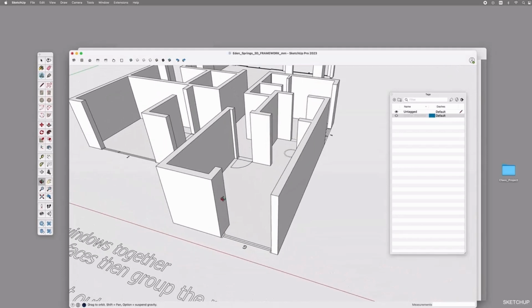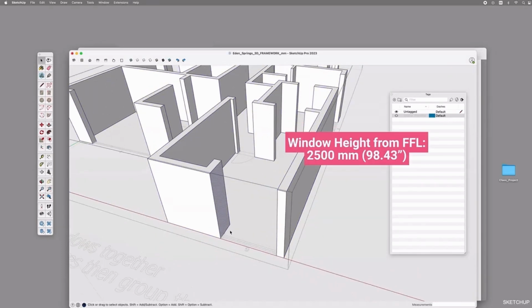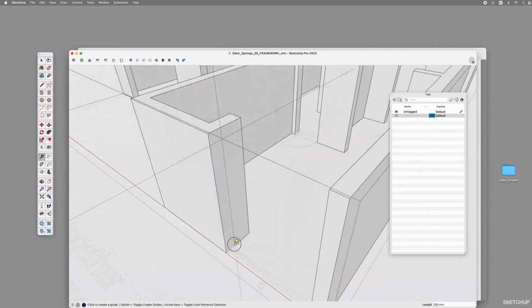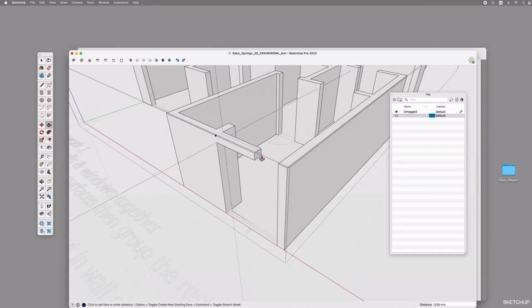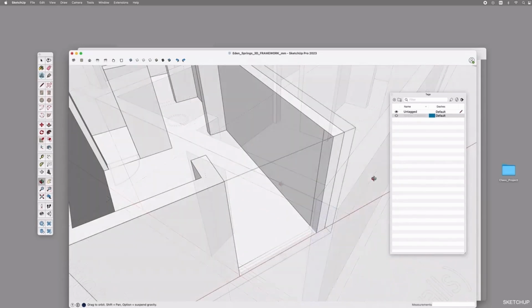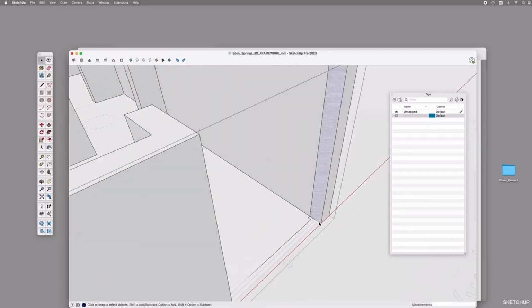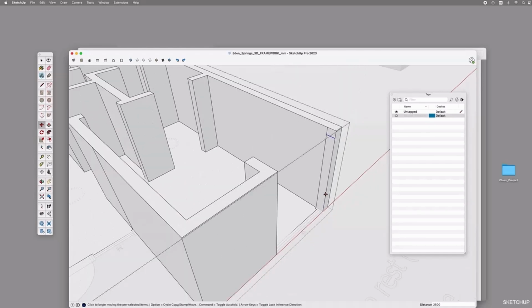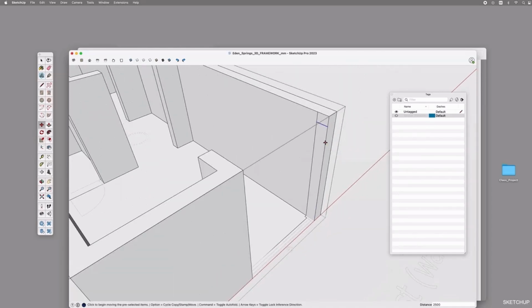We can now use guides to mark this. Or we simply copy the bottom line with a locked blue axis and place it as its height. I usually copy the lines, as I won't need to draw a line when using guides, but both approaches work. Then you simply push-pull the wall and use the interferencing endpoint like this. If the lines bother you, you can just remove them.